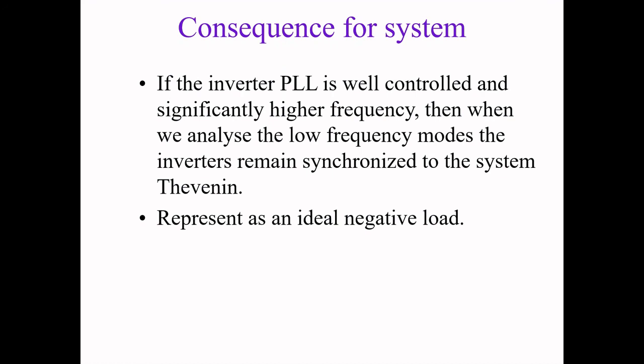And so if you were trying to come up with a representation at a crude level of what the whole of Victoria looks like, you could say, well, there's a few inter-machine oscillations, there's a few inverter-to-inverter variations, but by and large, they're all well damped. And as far as we're concerned, we can just represent these inverters as a negative load for the operation at one level of modeling.